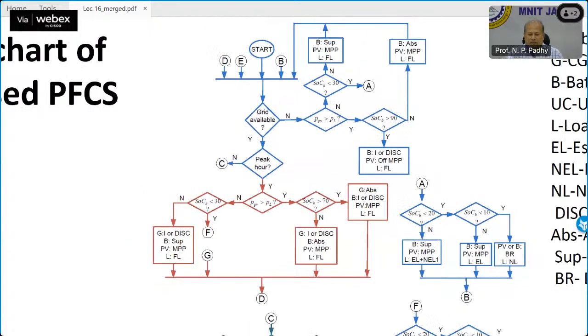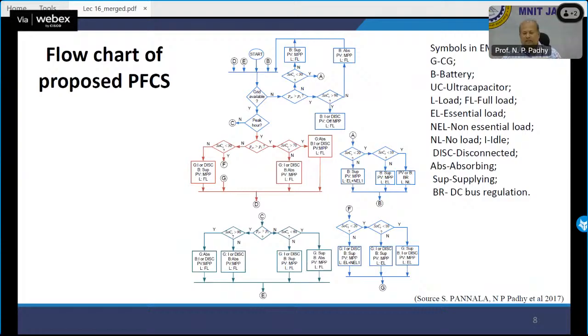Similarly, I request all of you, we have given different strategies for batteries. One category which is 30 to 70, another category which is 90, another category which is 20 to 10 also. Depending upon the smartness, you can keep the boundary. If the situation is too demanding, there is nothing wrong to charge up to 90 and to discharge up to 10. But if the situation is a very happy moment, then you can manage between 30 to 70 itself.